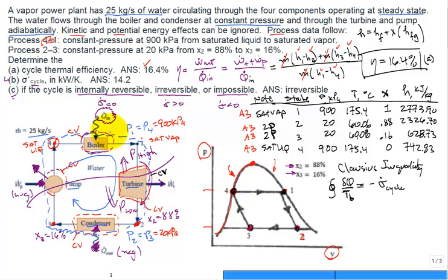So none of there, but I have to put a control volume boundary right here, and what I have is Q dot in coming in, in the boiler. So one of the parts of this integration around all the components for the whole cycle will be Q dot in, divided by the temperature at which it's coming into the working fluid in the boiler.